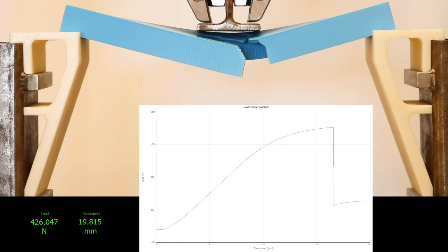What I'll do is I'll give you the load deflection data for both of those beams, and you can calculate what the moment of inertia was for each beam, and then look at how that compares to the stiffness of each beam, which is the slope of that load deflection curve.